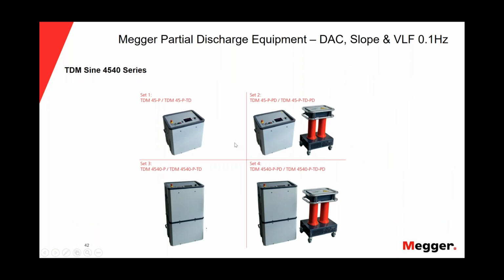We can have different options depending on what we are looking for. We can have the TDM 45 with tan delta and BLF only. We can have the TDM 45 with the BLF, the tan delta, and the partial discharge option. We can have the TDM 4540 with the booster only to have the BLF sinus and the BLF cosinus rectangular for the BLF test. And we can have the TDM 4540 with the booster, which will allow us to do the BLF with the sinus wave shape and with the cosinus wave shape.